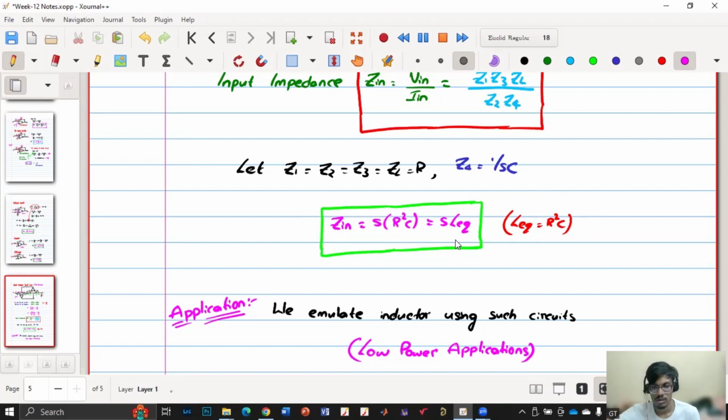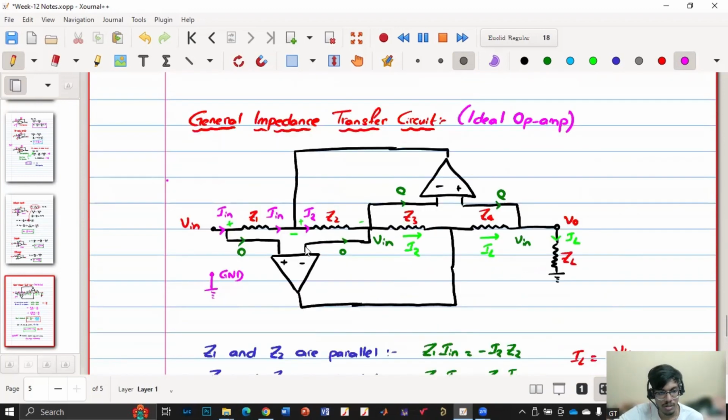Can we scroll up? I'm curious about the circuit. Here Vin and Vout are virtually shorted, right? Yes, basically our V naught is the same as Vin, but this need not be our output voltage, because I have represented V naught as connected to another resistor, but this may or may not be our output. The entire objective is that I connect a circuit so that when I look at it from the input point, it will look like an inductor. So this entire circuit has two terminals, one is Vin and ground. Between this Vin and ground, it will act like an inductor.